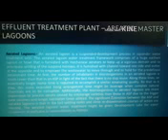So in this process, next we'll go for the trickling filters. A trickling filter in wastewater treatment is a bed of crushed rock or other coarse media approximately 2 meters or 6 feet deep and up to 60 meters or 200 feet in width. Settled sewage is sprayed over the bed surface and is further cleaned as it flows downward, interacting with cloudy layers of microorganism slime attached to the media.